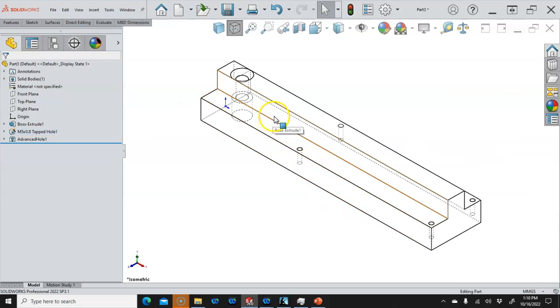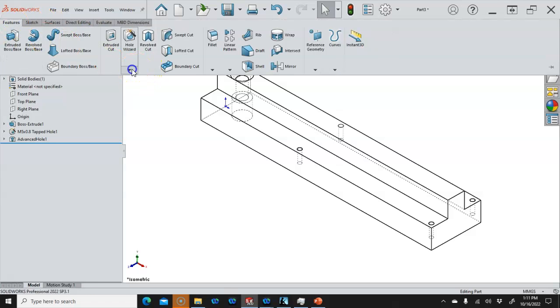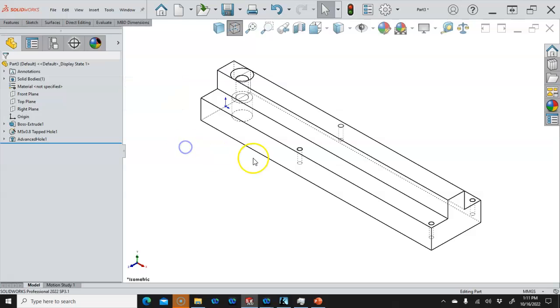All right, and then the final group, let's go into the face. For the, I always forget. For the thread, we need to either have the shaft diameter, and I prefer to cut, but if we wanted to extrude the thread, then we would need the minor diameter.